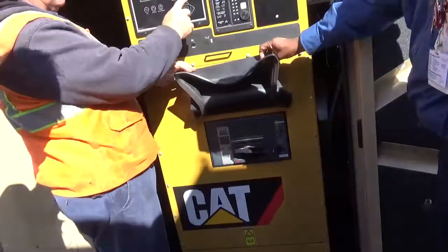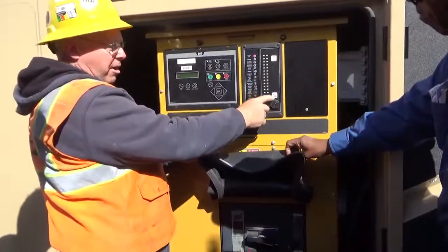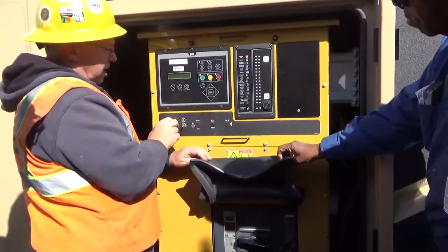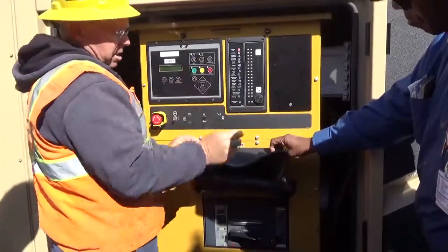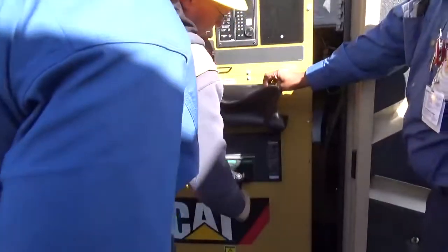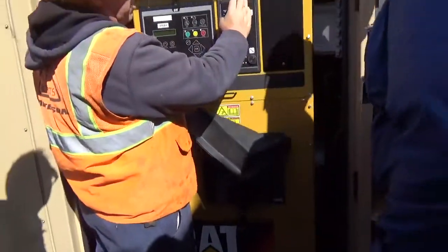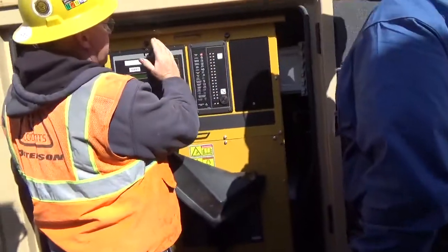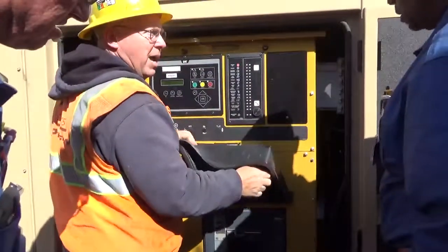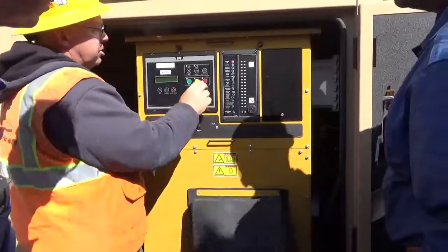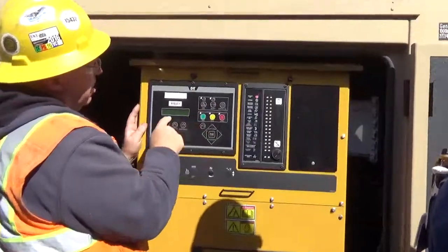So the first thing you have to do is go to stop, which now is going to give you not in auto, and that's normal. You've got to reset this first. Once you reset it, then you can reset this, because if you don't, watch what's going to happen. The alarm's still here, still red. It won't reset because you have to do this first. So you go to stop, reset right here.